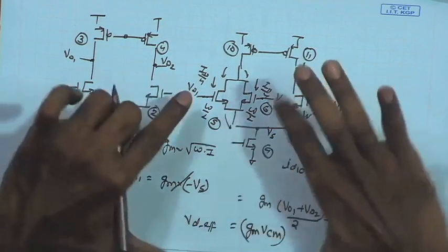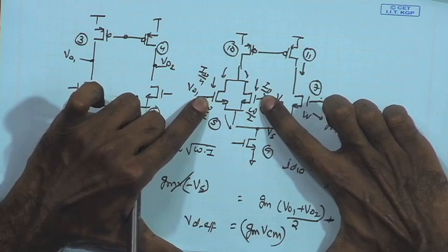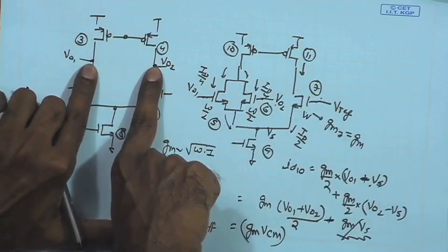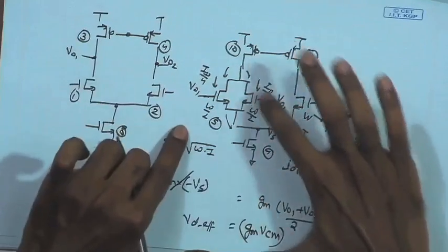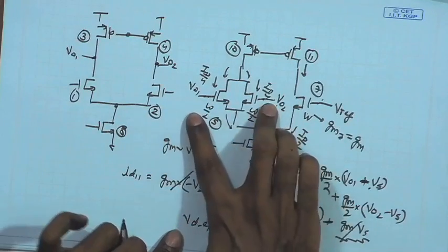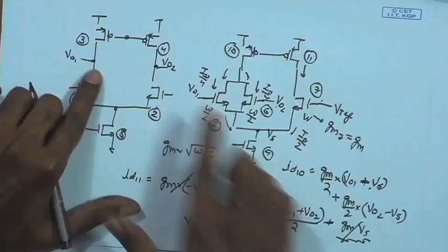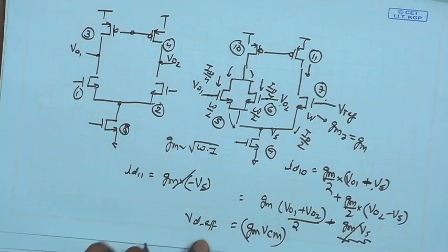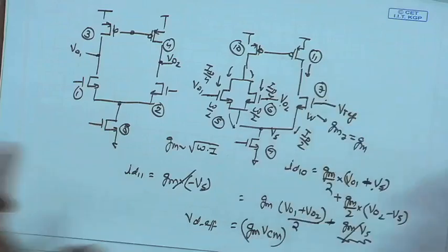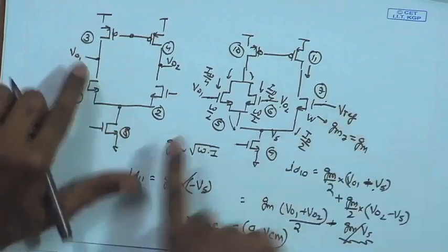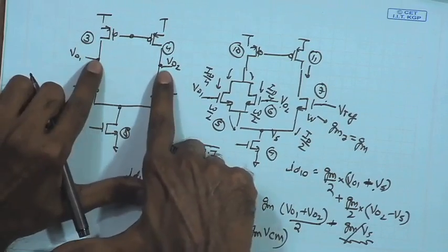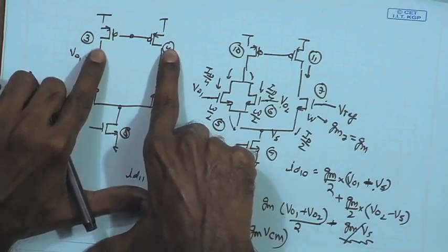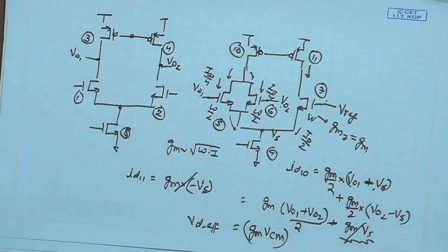So, basically this split differential pair is extracting the VCM of the first stage. It is helping us in obtaining the VCM in an indirect fashion. We have got rid of that resistive divider, and with the help of this split pair we are able to extract the VCM. Now, if you look at the polarity, once again if VCM goes up, it means both the signals are going up, or the common mode level of the first amplifier, the main differential amplifier, is going up.